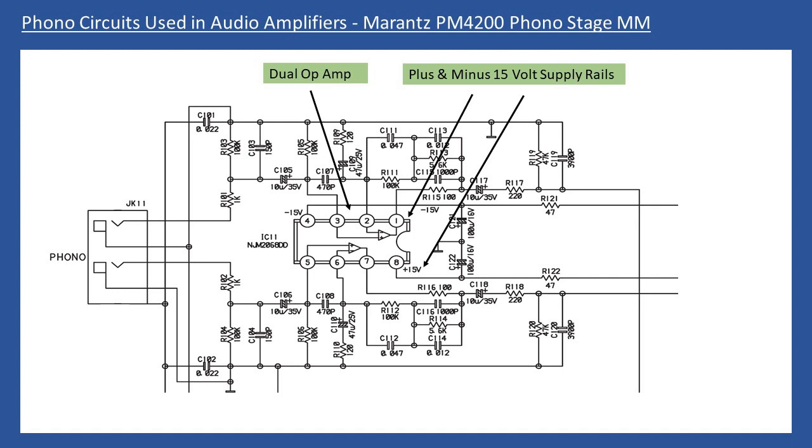So what this circuit is doing is the same as the one previously. So it has to do the equalization, it also has to do the pre-amplification to get it up to that line level before it's then fed maybe into the tone circuits of the amplifier, or if you choose to bypass them via the volume control, it will then feed into the voltage amplifier stage of the main amplifier board, or the voltage amplifier stage of the power amplifier.